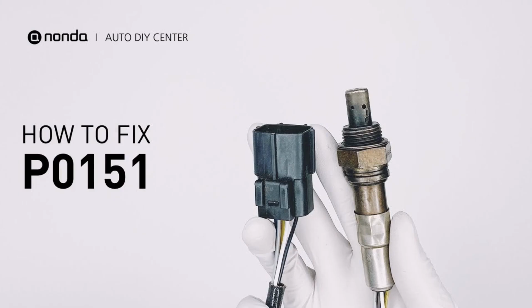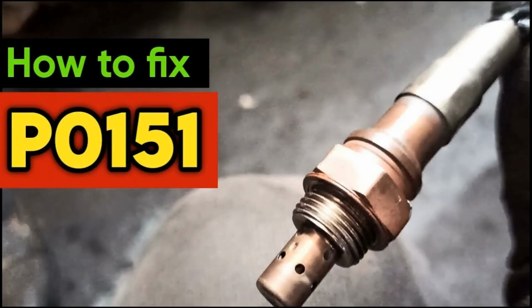If your analysis tool has recorded the P0151 code, this guide will provide you with the essentials you need to know for troubleshooting. What does the P0151 code mean? Diagnostic Trouble Code, DTC, P0151 means O2 sensor circuit low voltage, bank 2, sensor 1. This means that the oxygen sensor voltage has been below factory specifications for some time. Code P0151 warns of an oxygen sensor fault upstream of bank 2.